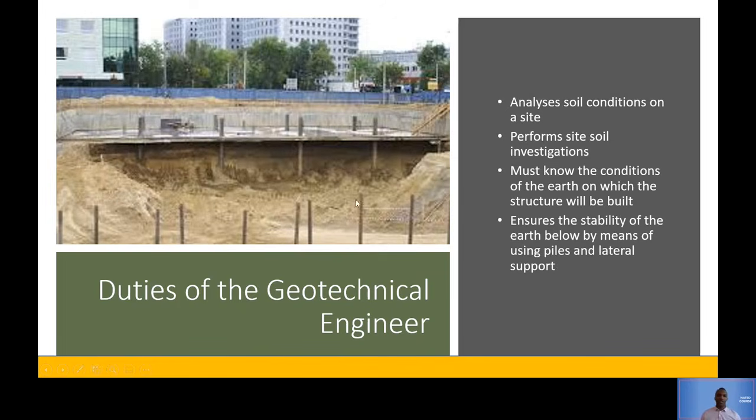So what all of this means is that based on the site conditions, he will then design. For example, if the site soil is sandy, then he will put piles. But if the soil there is actually rocky ground, there he will not use piles, but he will use lateral supports. He will use shallow foundations and all those types of foundations.